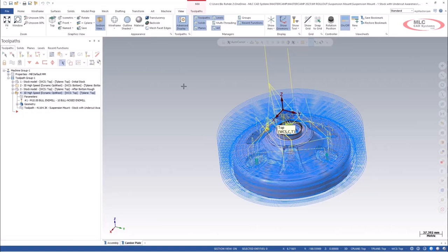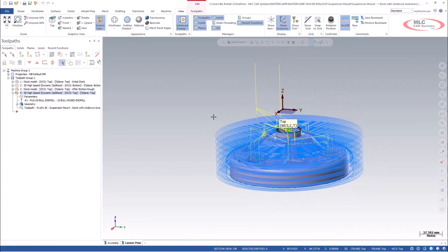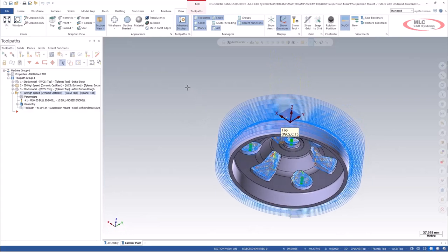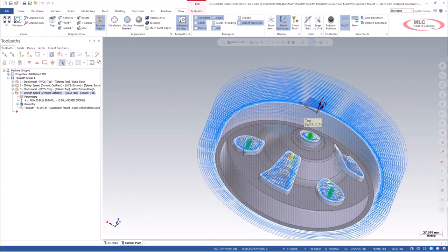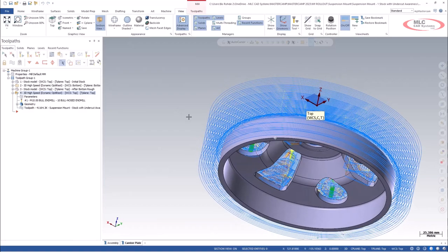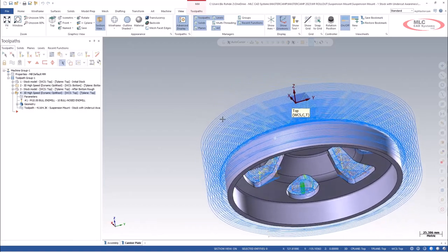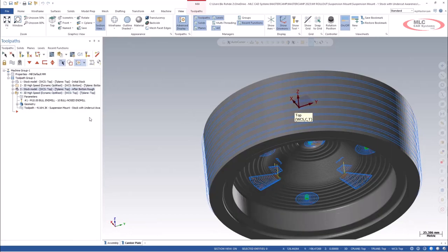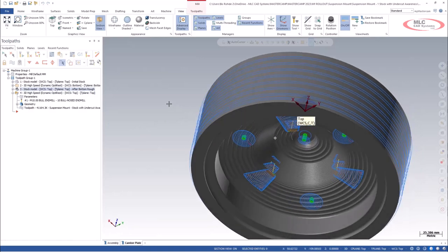And it looks like we're about done. So if we look at this toolpath now, everything appears to be normal. But when we flip this over, notice that the toolpath is just going below this bottom surface. So there's no excess cuts necessarily that don't need to be made. If I turn on my stock model, it kind of shows a little better.